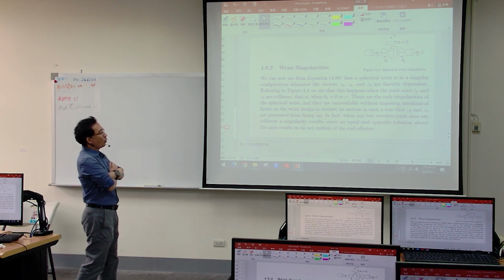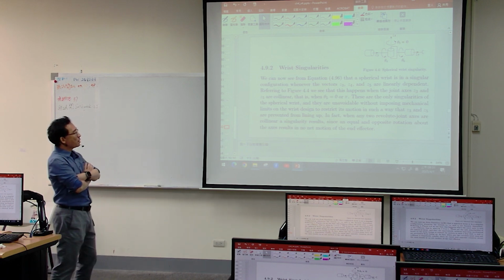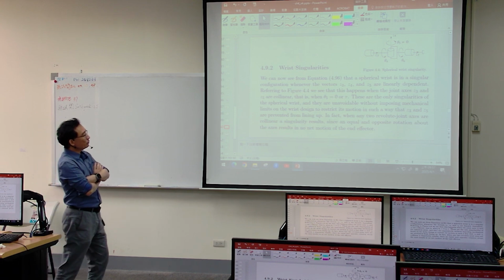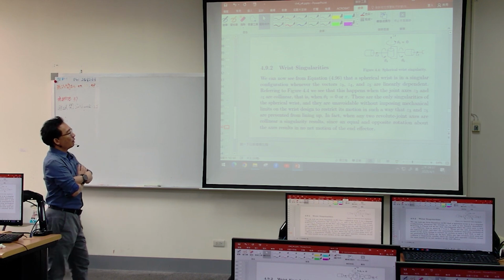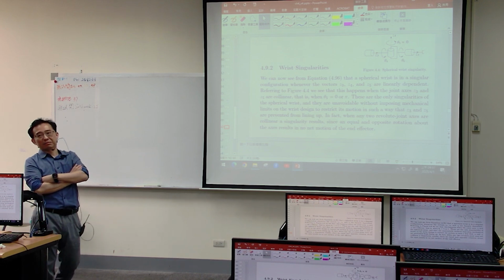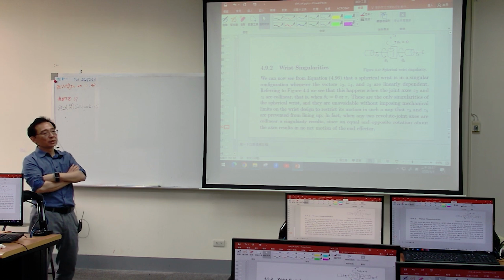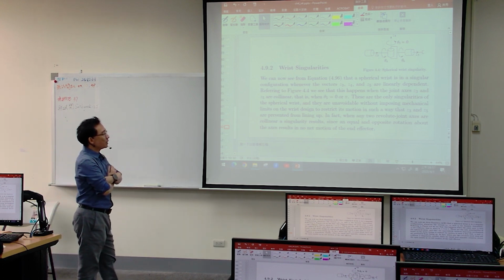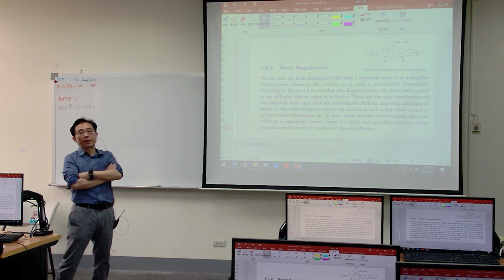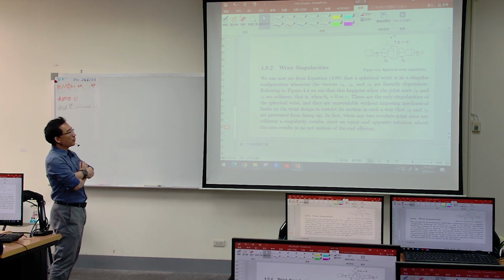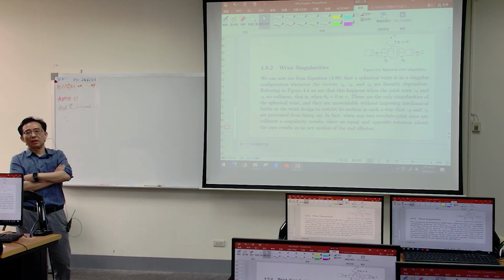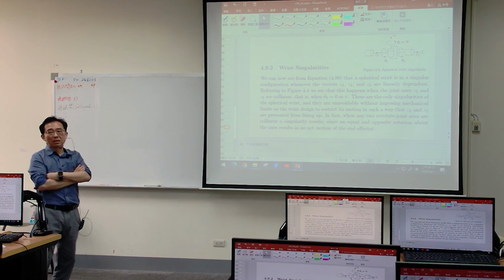Over here we define what the singularity is. It means Z3 and Z5 don't make any difference for the robot. When theta 5 equals 0 or pi, whatever Z3 and Z5 do, they do not show a significant posture difference. So it means singularity.